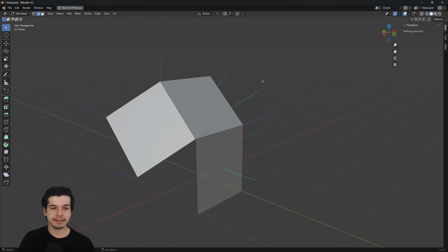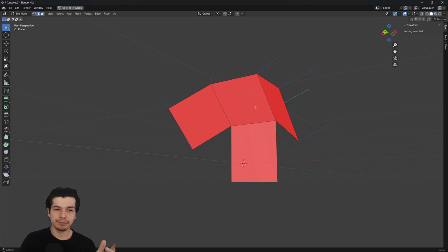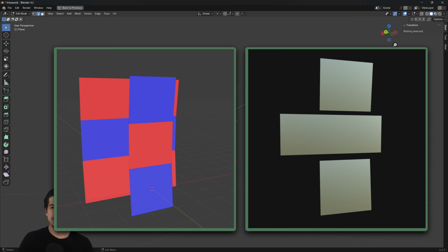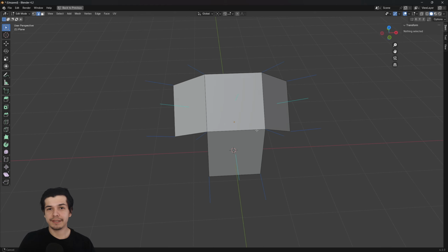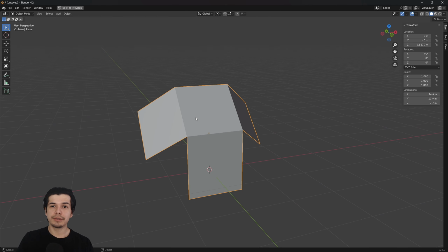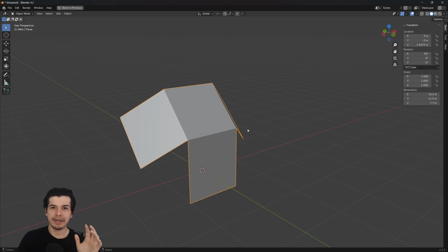So as you can see, we have so-called normals on our meshes, and these normals help us to do certain functions with it. It also helps us to orient the way the face or the mesh is looking at. This would be a negative, and in some software this can result in transparency. Basically, you would see through. Where you rotate, suddenly you see the surface. So this is not in Blender, but this could result in darkening areas and sometimes the object not going the ways you would want them to go. So it's good to know where they are facing.